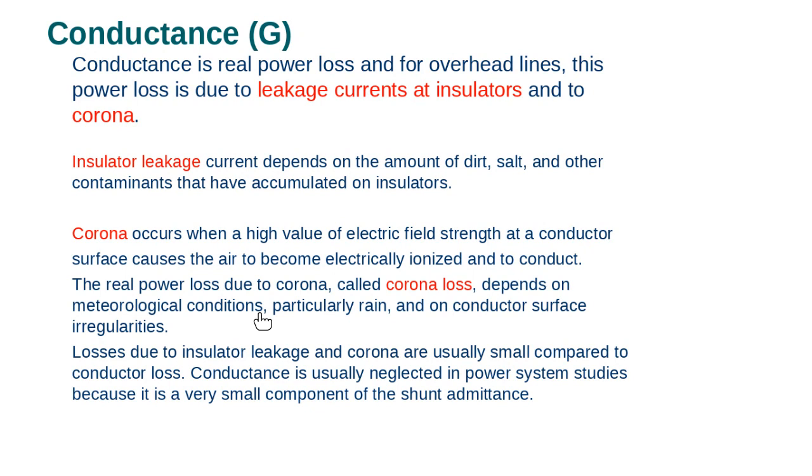You will see this corona because of the ionized air, and you see it clearly at night. In the morning it is hard to see, but still it is there. You can also hear the noise if you are close to a transmission line, because of the leakage of corona. Compared to conductor loss these are small, of course, but they cause interference also.